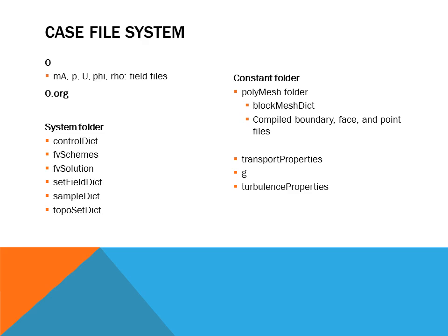You can also implement turbulence properties, but in this kind of case, when your crossflow is half a meter per second, you're going to have a laminar case no matter what, so there's no real point. Unless you choose flow baffles to increase the turbulence. That's not going to be an issue.